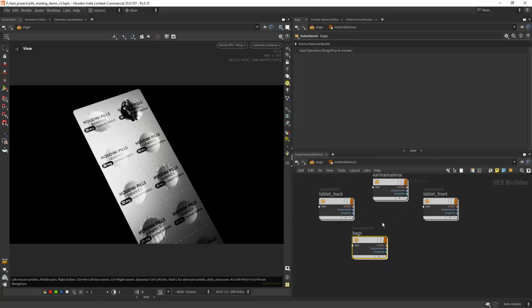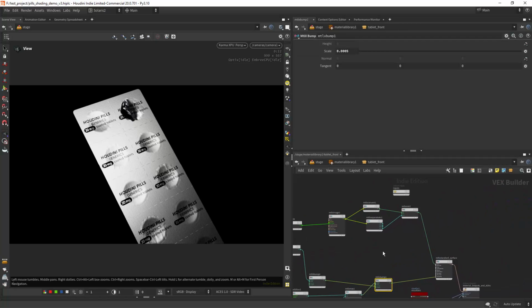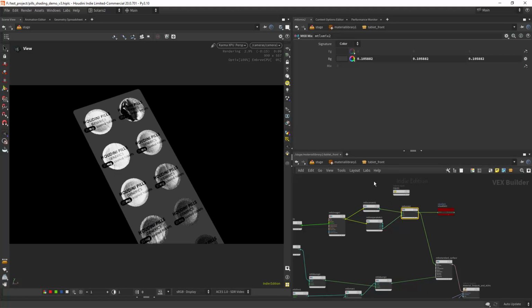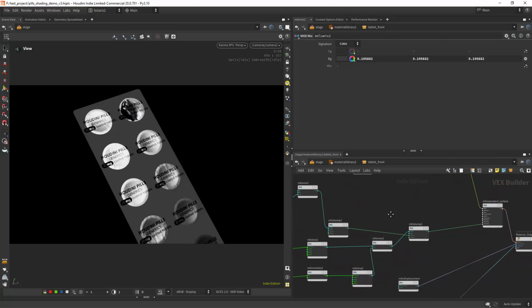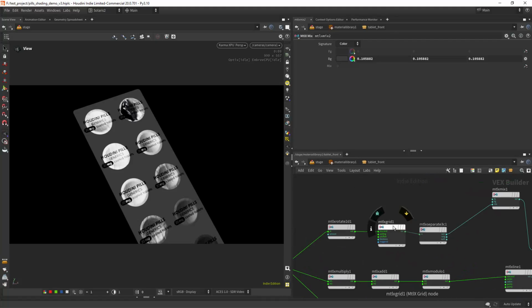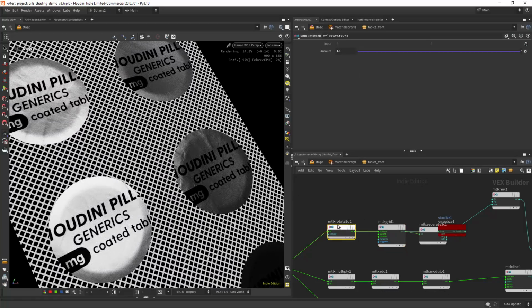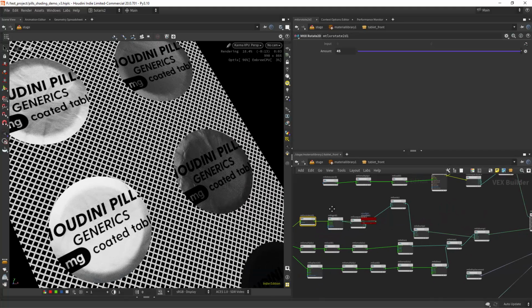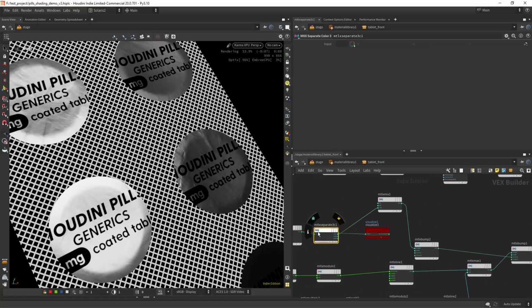So let's have a look at the second shader, tablet front. I also have the same texture in here repeating, so it's this one on the outside, ignore this inside. In the same exact position. And let's see, the first pattern is actually pretty simple, it's just a grid, as you can see. It's just a grid that I rotated 45 degrees with a MaterialX rotate 2D, or you can also use a place 2D. Then I'm just extracting one channel